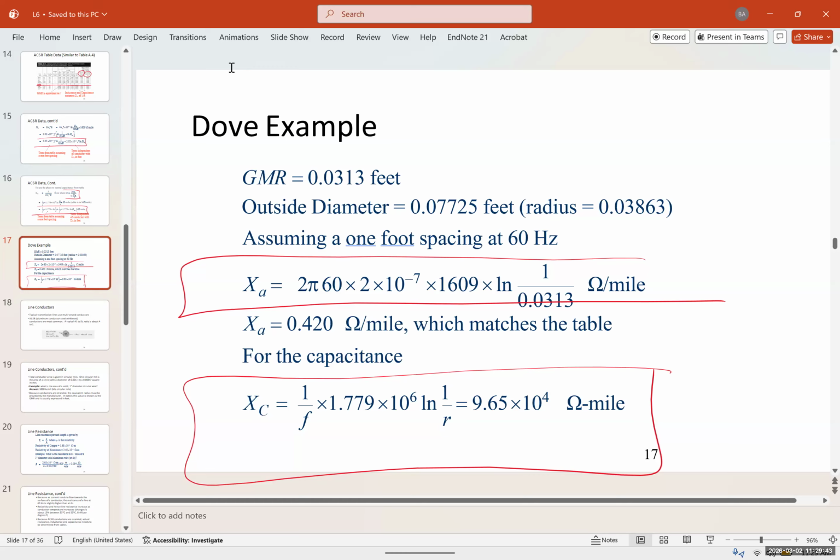Now, you may ask, is there a difference if we have different wires? The majority of the wires that we use, 99% of the wires, do you know what material they are made out of? Aluminum, yes. They are aluminum, and usually they have a small steel core as well to reinforce it, because as you know, aluminum is a little flexible. If you put it on two poles with half a mile distance, you're going to have sagging, so you need a core that supports it.